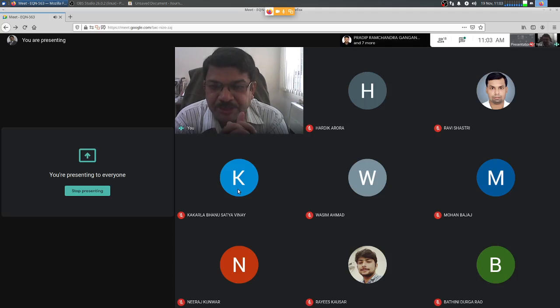Until you have a mechanism at hand, the structure will continue to support the load. The load carrying capacity might be reduced somewhat, but it will not go to zero unless the structure is reduced to a mechanism.